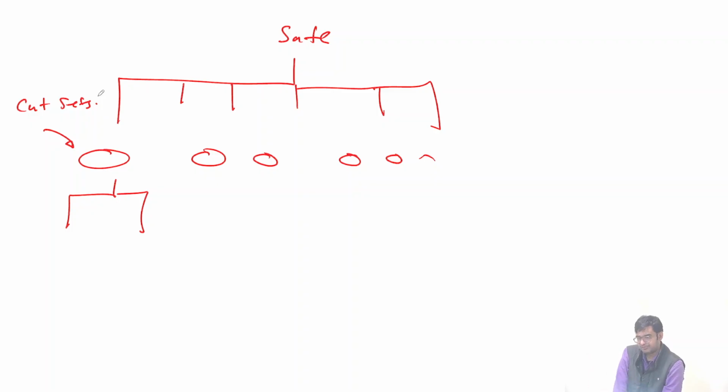Because of this large number, it is very common that you might miss one or two failure modes. You have to note them down. One or two you might miss, it's possible. In that case, this will start underestimating. It will give a smaller failure probability. Why? Because these are unions, this is series failure.